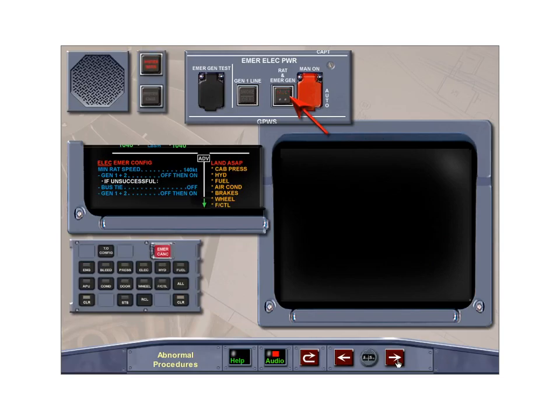The initial warnings for the electrical emergency configuration fault are a continuous repetitive chime, the master warning light, the ECAM warning, and a momentary fault light on the RAT and emergency generator push-button switch as the emergency generator comes up to speed. The lower ECAM display is lost due to no power supply. When required, the electrical page can be displayed on the upper ECAM display by pressing and holding the electrical push button on the ECAM control panel. Touch the electric push button to display the electrical page.